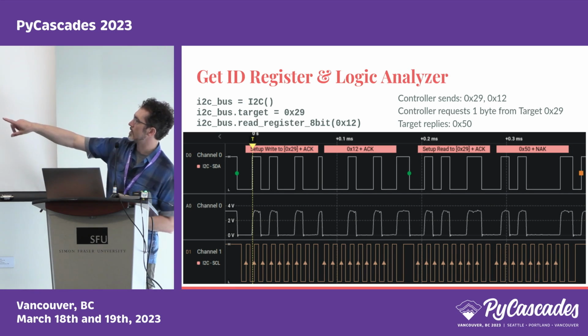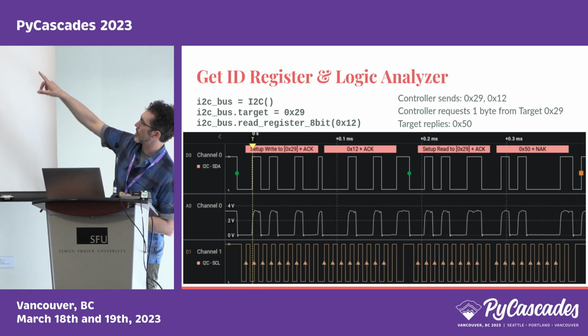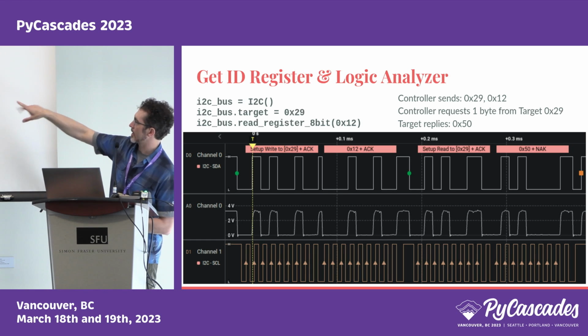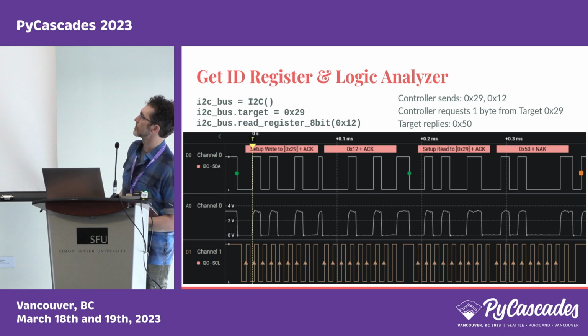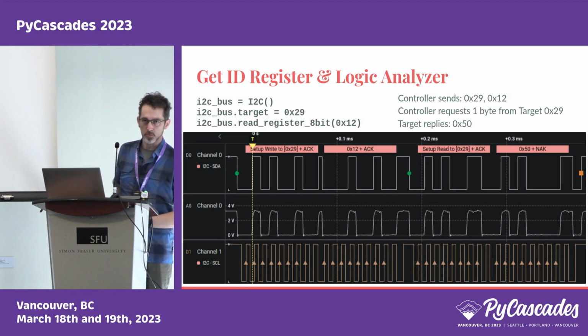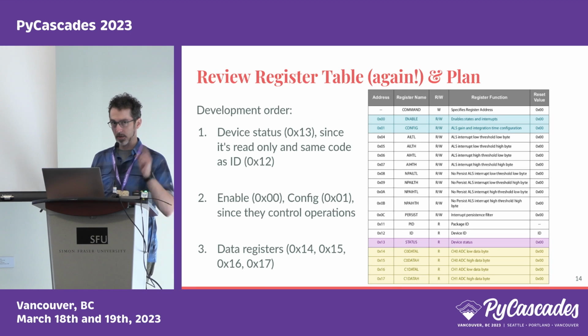And then in the middle here, these are the actual voltages that we're seeing. This is the digitized representation, but the actual high sample rate, you don't capture that on the I2C bus. That's what the logic analyzer is doing. But you can see that it's not perfect square waveforms. There's no such thing. So we've been able to read 1 register.